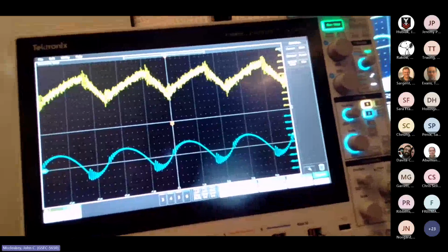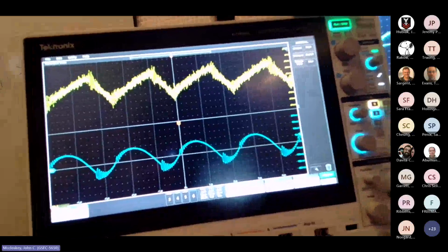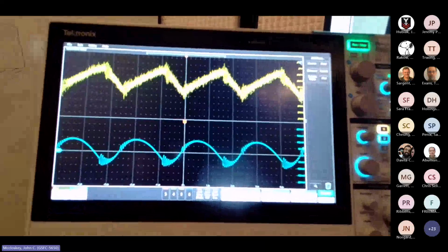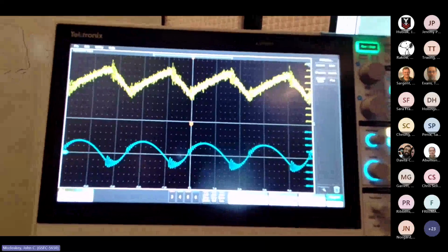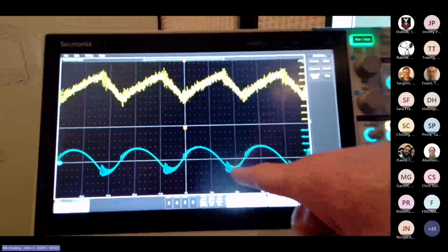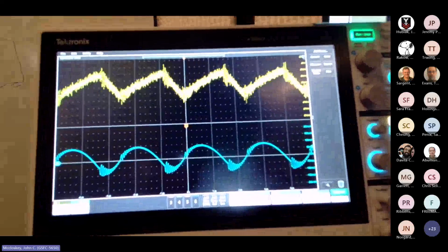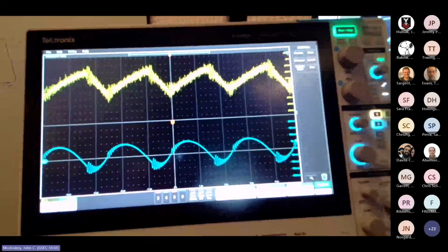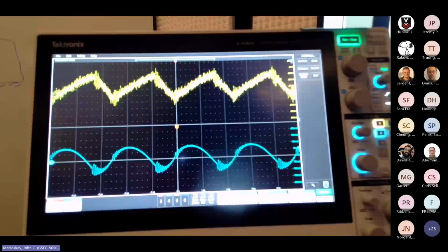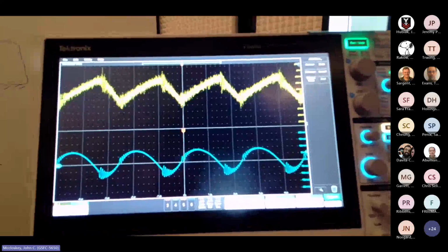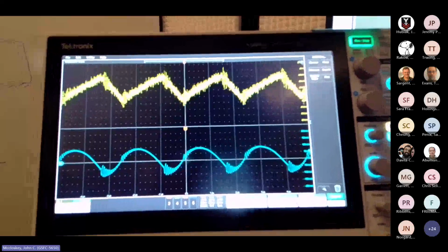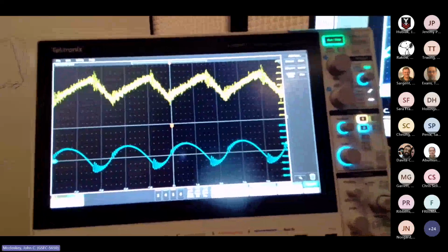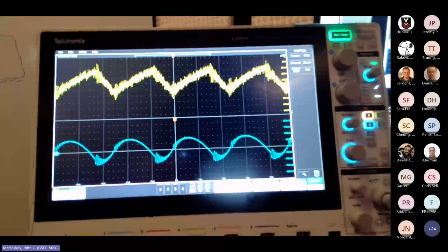That's the sort of stuff. And remember, this is a test and measurement discussion, not so much a design discussion, but that's the sort of thing to pay attention to in design considerations: that ripple is the sort of thing you need to filter out. But as we'll talk about the specifics of differential mode and common mode, those two different types of measurements will help you diagnose which problem you're dealing with, because the solution space is different. So this gives you a look at the time domain of what this signal looks like.